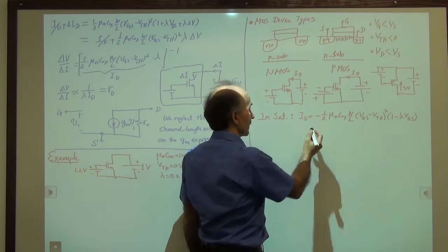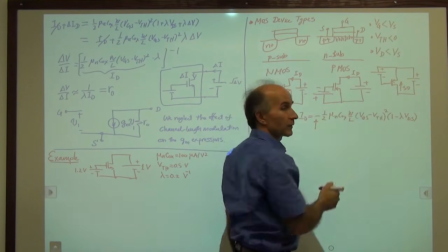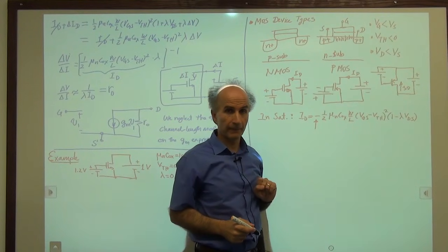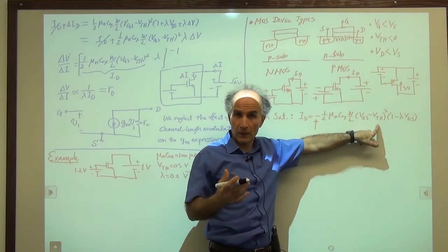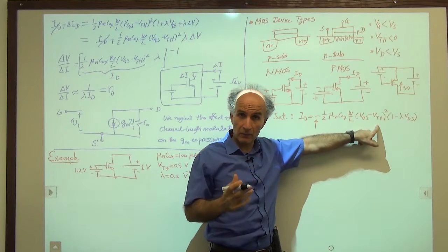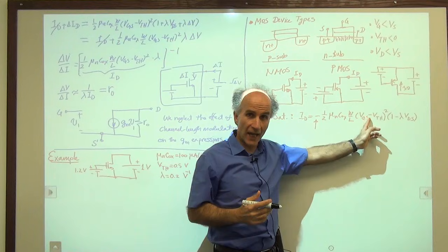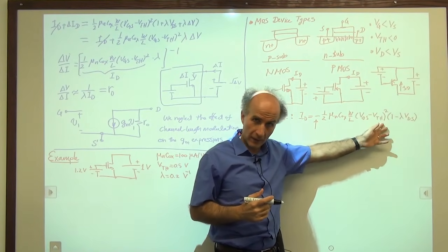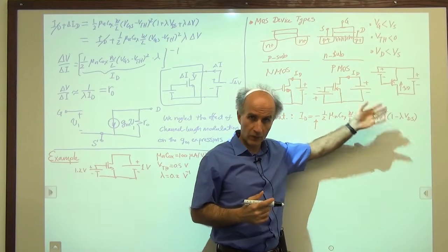So this negative sign was to be expected because we said the drain current of a PMOS device in this direction is negative. VGS minus VTH, we didn't fuss about them. Are they positive, are they negative? Doesn't matter because this difference is squared. So long as this is VGS and this is VTH, VTH is negative, VGS is negative, we are subtracting them and then squaring it.